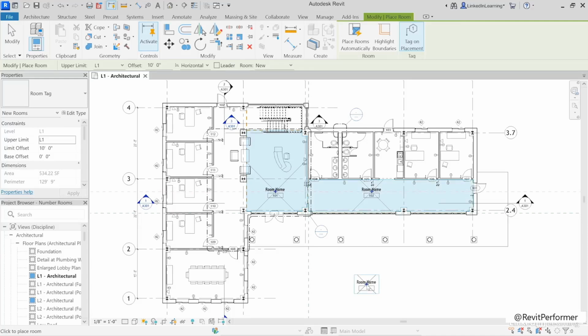Now, if I go back to the room tool, you will see that I'm able to click the next room and it will sequence to 102. So if you remember the way that Revit numbers things, we saw this with grid elements and some other elements as well, it always numbers in sequence. So that's why it's important to stop, change the number, and then continue from there.